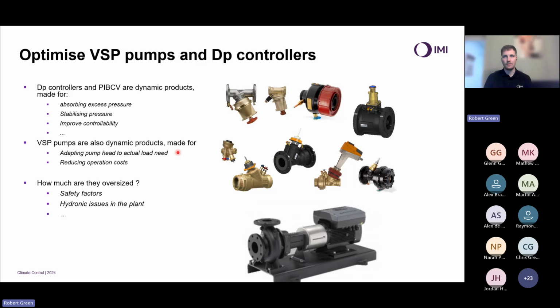We go to a pump manufacturer and say, okay, Mr. Velo, Mr. Grundfos, Mr. Lowara, whatever, can you provide me a pump that will do me 5 litres a second at 110 kilopascals? And they say, okay, Rob, yes, here's my selection. And again, they're going to probably select the pump that's able to maybe deliver 120 kilopascals, maybe more. Again, it's oversized. So the key thing is, these pumps are variable speed.